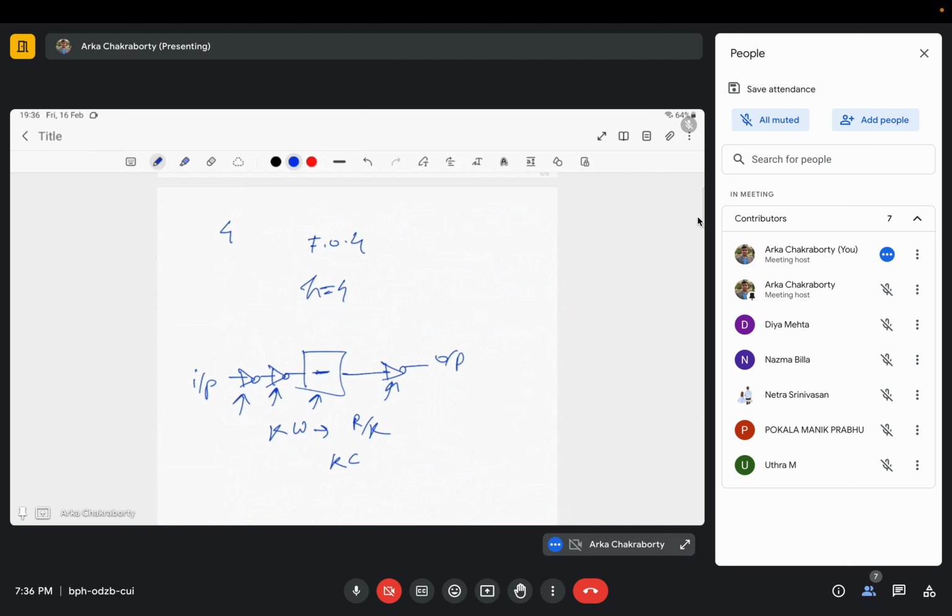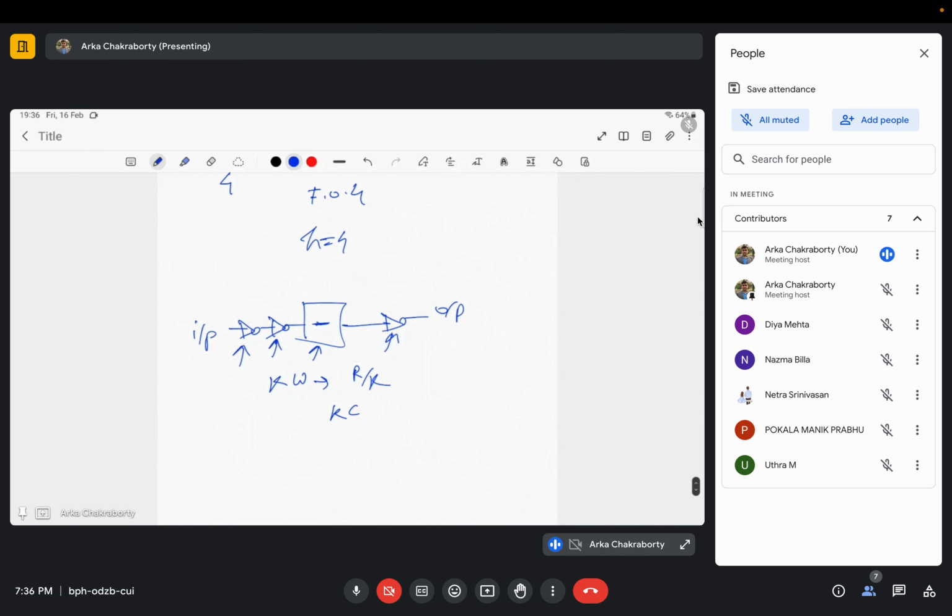you will find, if you take the derivative of the energy and find the least amount of delay, that we get the least delay when all the stages present in a circuit are doing equal amount of work. Okay, when all the stages are doing equal amount of work, at that time the delay that we encounter is the least.